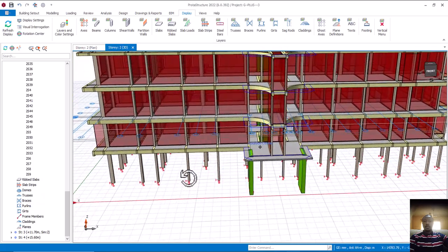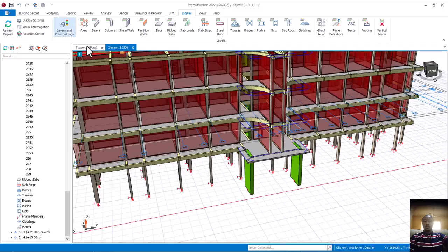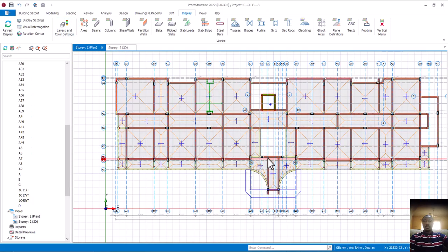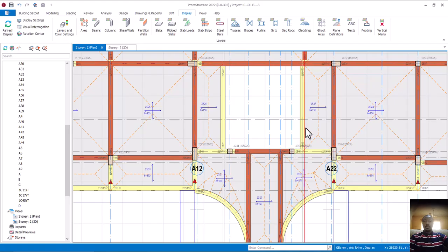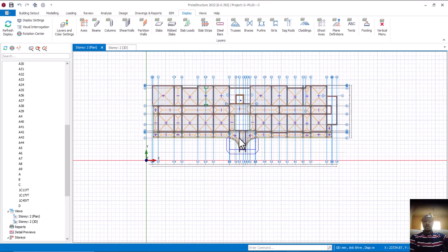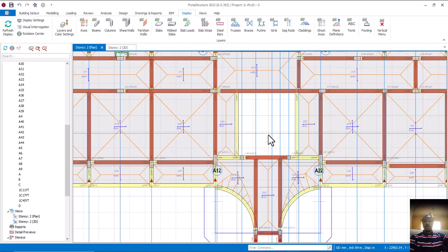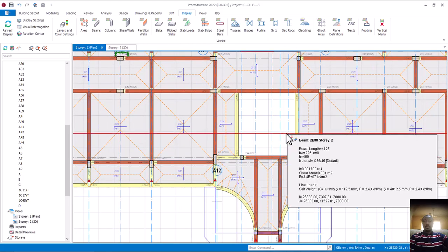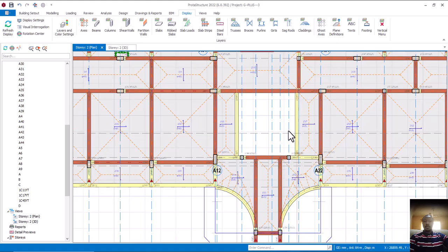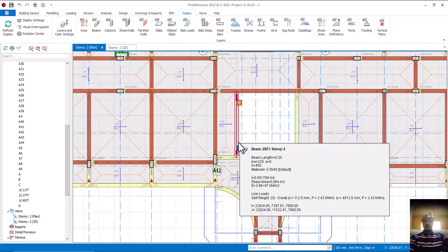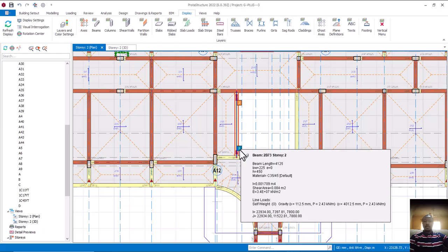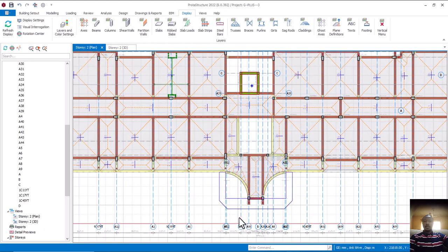Let us go there. Okay, even this particular place, we don't need this one. There's need for a handrail. We can put the handrail wall there. Is that okay? We can calculate it. Even without the loading, automatically it will carry the handrail. The handrail is not too much, but at least for design sake, you can put a small load there. Like, let's say, a maximum of 1 course of block. Is that okay? And you know how to calculate that, isn't it?